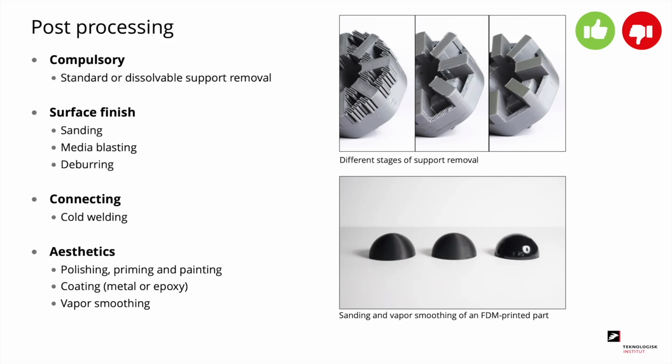You have to remove the support structure, which takes time, but you also have the opportunity to have a nicer surface finish of the part, create connections between different parts by cold welding them together, and get a better aesthetics by polishing or coating or vapor smoothing the parts.